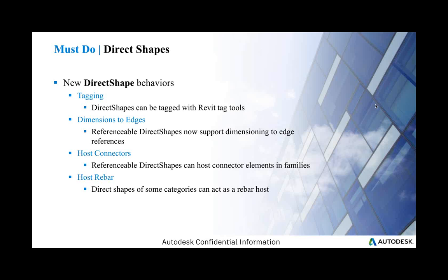So we're adding more and more functionality to the direct shape so that it can support all of the different needs. And now we've added the possibility to tag direct shape elements, dimension to the edges of a direct shape, add host connector elements in families, and set up host a rebar in a direct shape. So you can create concrete structures represented by direct shapes and host rebars in those.